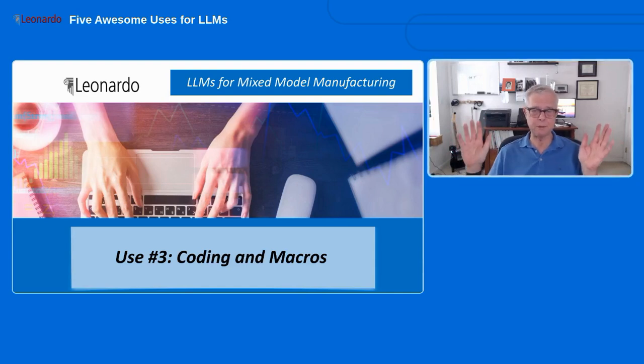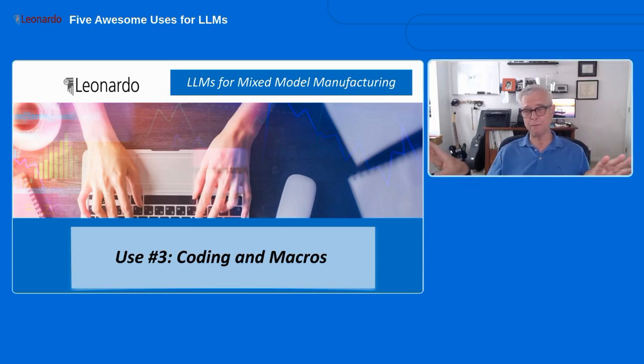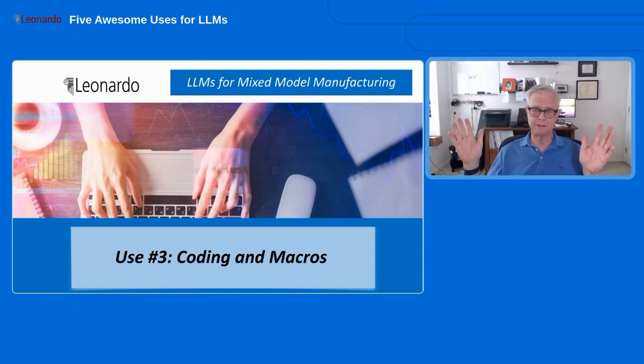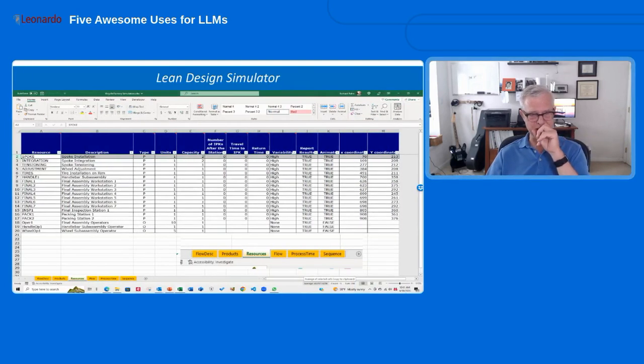For example, a simple example, there's a takt time calculation formula in Lean. You've got effective work minutes divided by volume, or your demand. So it's minutes per unit is takt time. I would not rely on ChatGPT to calculate takt time for you. I would have it generate a macro that uses your data in an Excel spreadsheet and does it for you. It's a very simple calculation, you can just add the formula yourself. But as an example, for any kind of data processing, I would not rely on ChatGPT or these other tools.